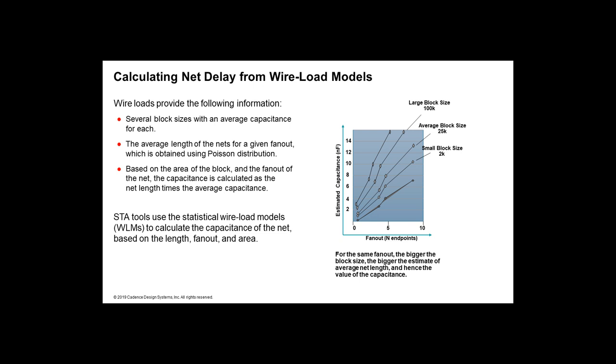And so you can also generate custom wire load models based on your design from specific place and route tools, and you can use those instead of using the statistical wire load models that are provided by your library vendor.